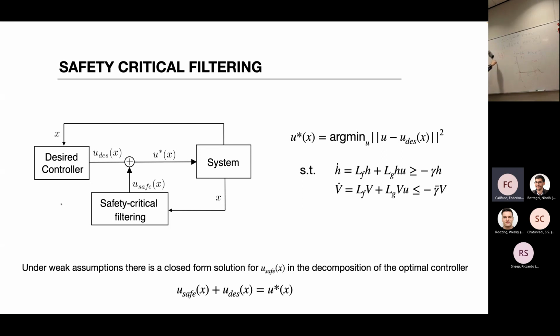It turns out that if you choose a CBF which is minus the kinetic energy of the system plus a constant times the CBF that you want to use for doing obstacle avoidance, which depends only on the q variable, then for a sufficiently high constant alpha E, the safe set of this one tends to the safe set of that one.